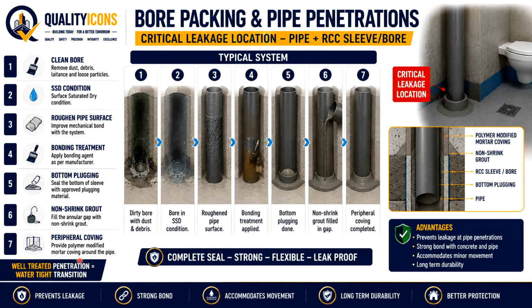Bottom plugging should then be completed using the approved plugging material. The angular gap is filled with the specified non-shrink grout only.